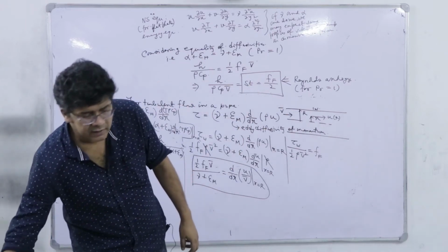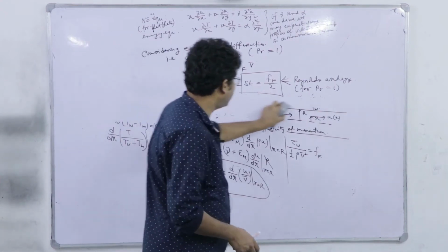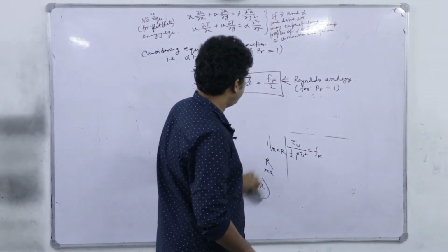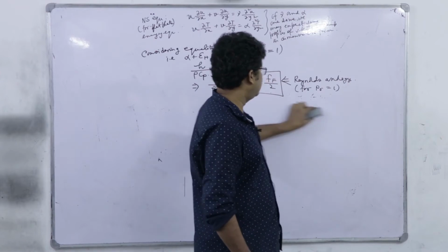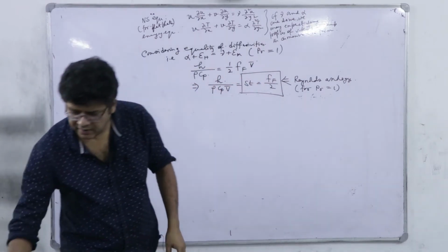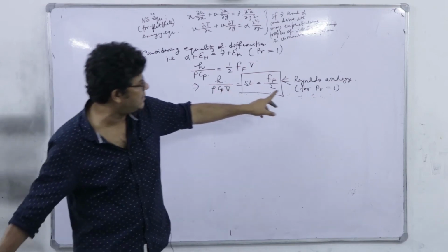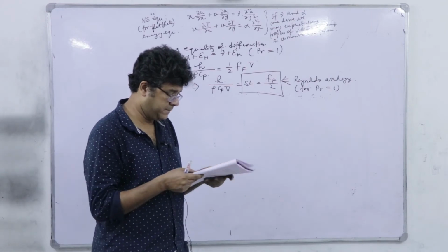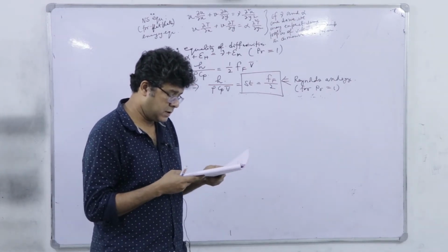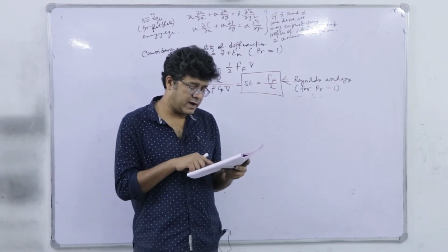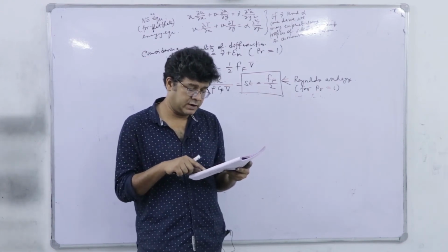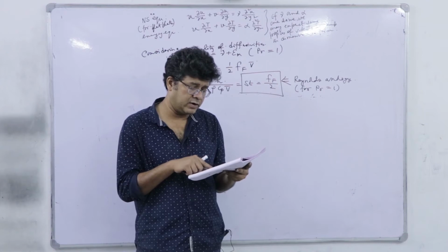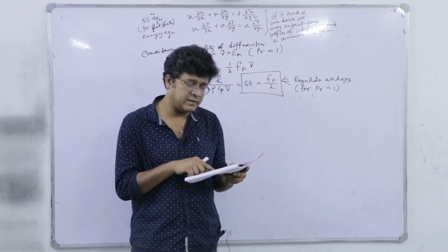Now, the Reynolds analogy was later generalized by Prandtl, and here you see that it is a very crude, rough analogy and valid only for Prandtl number equal to 1. So, what I am trying to point out regarding the Prandtl analogy is that Prandtl provided a more realistic picture of turbulent transport by assuming the momentum and heat transfer occur through eddy exchange or eddy transport in the turbulent core and through diffusive transport in the laminar sublayer.